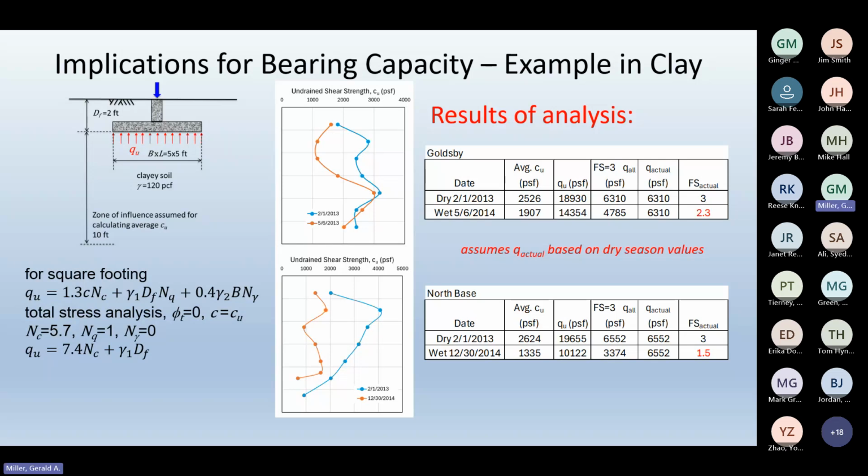The other thing, and we may talk about this in the part 2 course, is that wetting also affects the settlement behavior. And if these footings are on a compacted fill and you get significant wetting, you can have significant wetting-induced compression. And that may be more of an issue than stability, again, because we often give such low allowable bearing pressures. Questions?